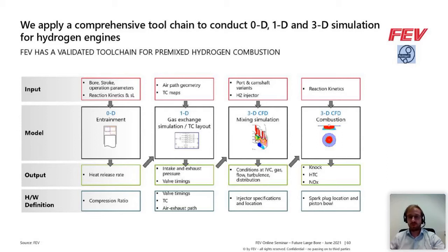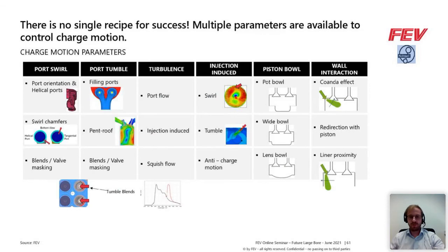For that purpose, we've also performed pressure chamber tests to validate the spray models, which is really very important to the mixture formation optimization. And then finally, of course, we are also performing 3D CFD simulations where we can also optimize parameters like the piston bowl geometry, and we can also use this as an interface to the engine mechanics, for example.